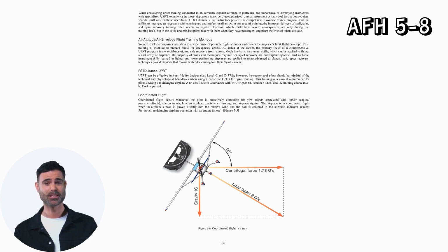FSTD-based UPRT can be effective in high-fidelity devices, Level C and D. However, instructors and pilots should be mindful of the technical and physiological boundaries when using a particular FSTD for upset training. This training is a current requirement for pilots seeking a multi-engine airplane certificate in accordance with 14 CFR Part 61, Section 61.156, and the training course must be approved.